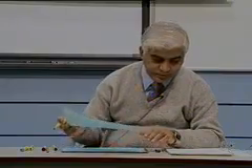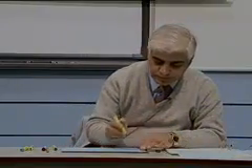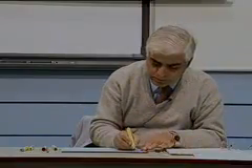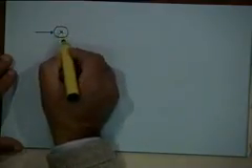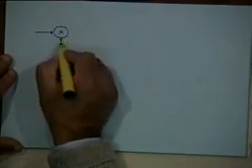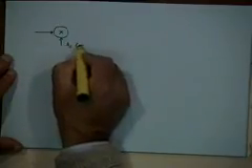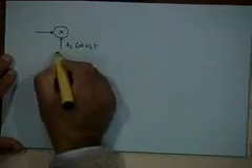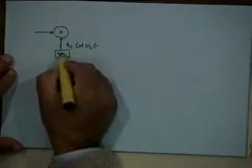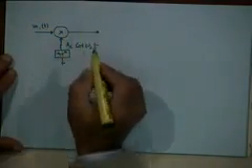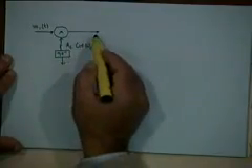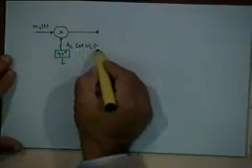Okay. To put it in the form of a figure, you have a multiplier for A_c cosine omega_c t. Let's say you have a 90-degree phase shifter here. Your message signal m1(t) comes here, and this is your modulated signal m1(t) times A_c cosine omega_c t.